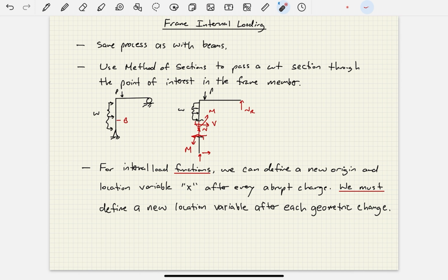You can analyze either one, and it also follows the same process of when we need to determine external support reactions. So, if you do method of sections, the free body diagram that you're analyzing, if it includes an external support reaction, then you would have to get those first, okay? So generally, same process that we saw with a beam, all right?